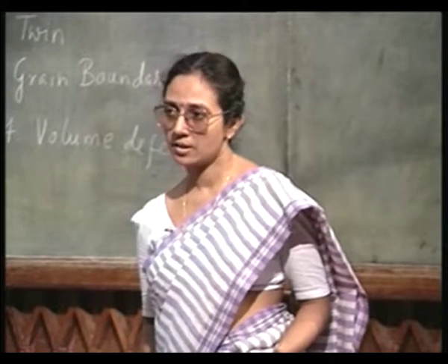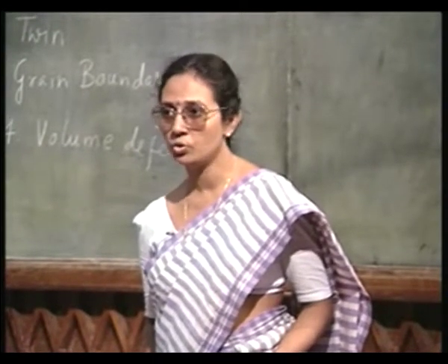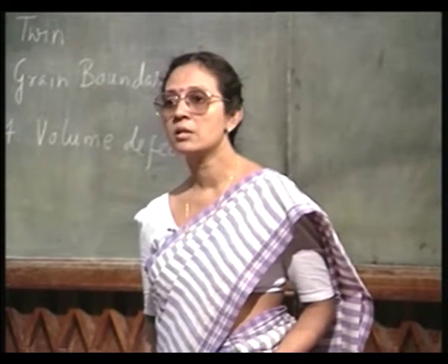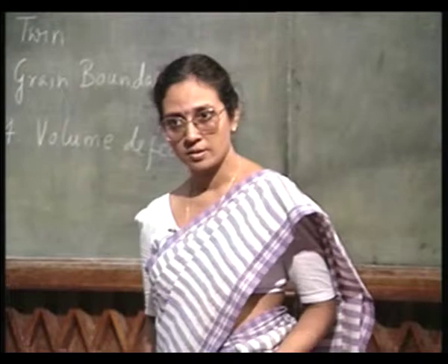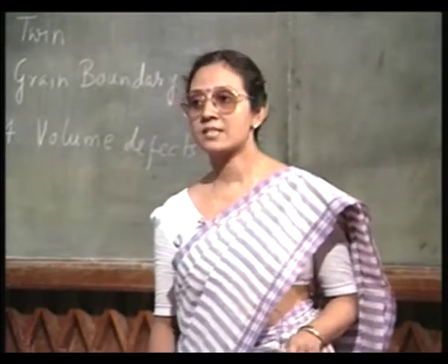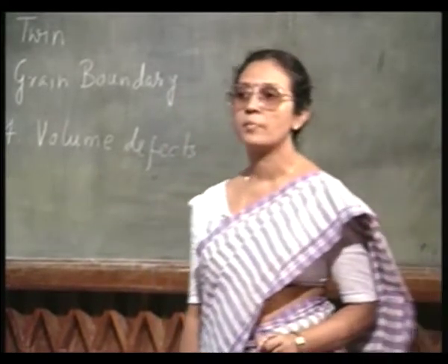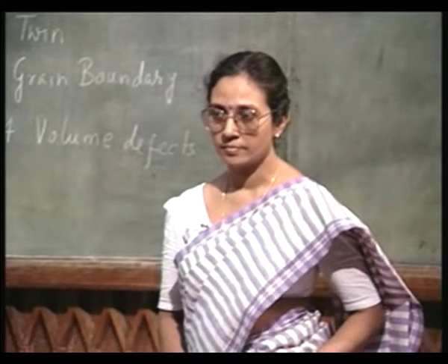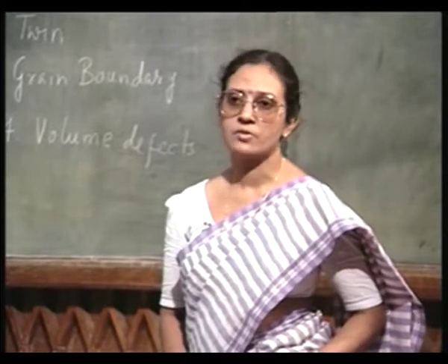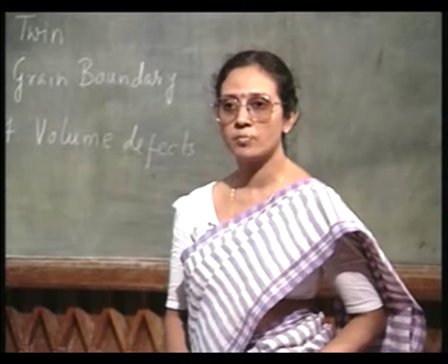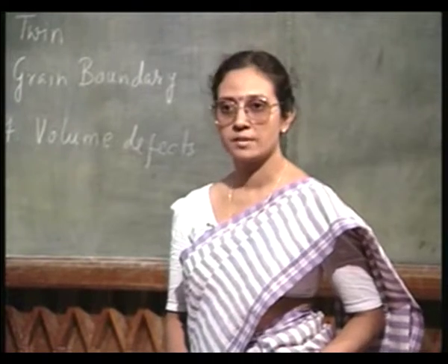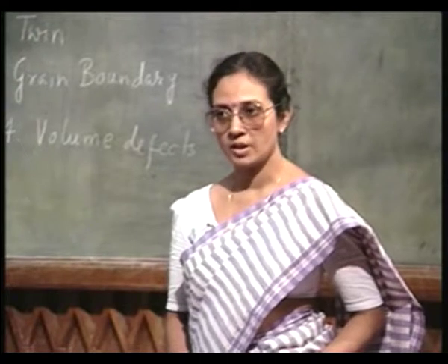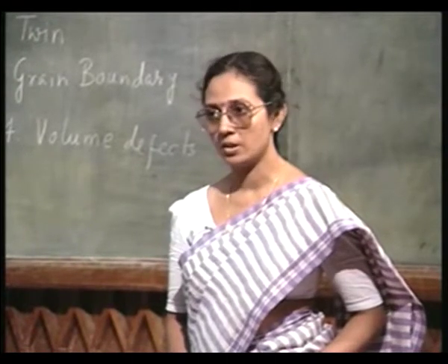But then as the crystal is formed and then finally it is cooled to room temperature, the solubility of these impurities will decrease, and therefore this extra material will be precipitated inside the crystal. They can get precipitated in various form. For example, if you have metallic impurities, it can form a silicide, titanium silicide or tungsten silicide. It can form silicides and get precipitated.